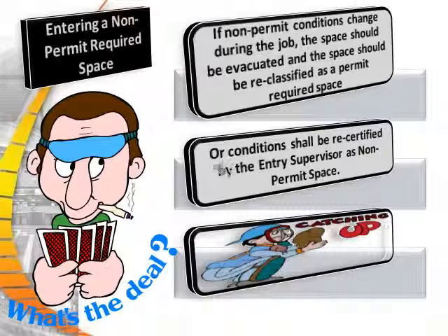If non-permit conditions change during the job, the space should be evacuated and the space should be reclassified as a permit-required space, or conditions shall be recertified by the entry supervisor as a non-permit space.